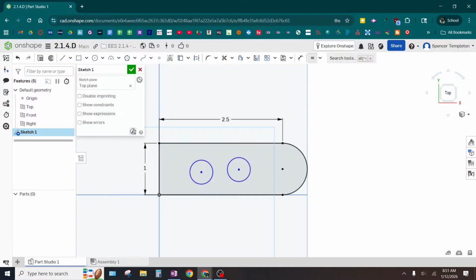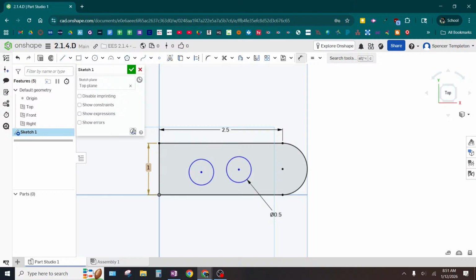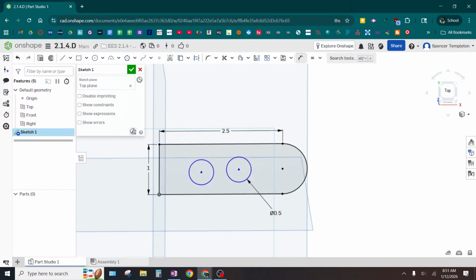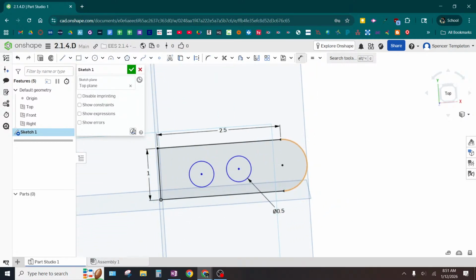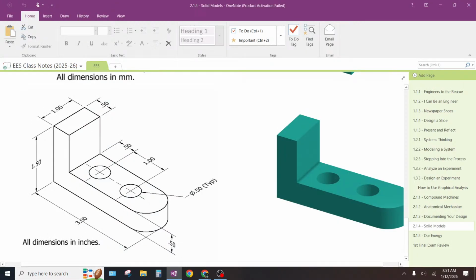I'm going to show that actually. I did show you before, but I'm going to show it again anyway. So this is what I would do. I'm just kind of prettying this up. Notice that I dimensioned the width and the length, or I don't know what you want to call these. Technically, for this orientation, it looks like a height, and this is a width, but it's going to be oriented like that. I dimensioned those. I didn't have to dimension this because it's just basic math. If this is a semicircle and this width is 1, then this is going to have a diameter of 1. It's going to have a radius of half, which adds up to this to give 3, which is the overall thing.